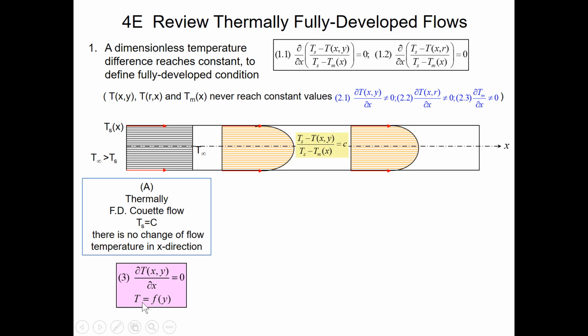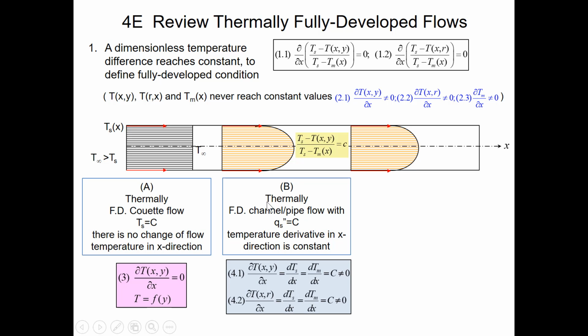That is, the flow temperature is only a function of y. For a thermally fully developed channel or pipe flow with constant heat flux boundary condition, the temperature derivative in the flow direction x is a constant, but not zero.